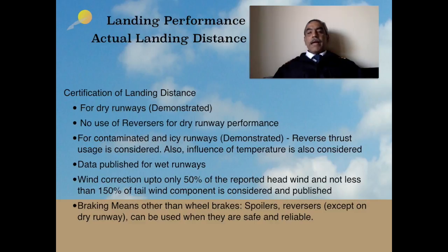For contaminated and icy runways, again, I'm sorry, this also has to be demonstrated. Except for wet runways, data has to be published. Whereas icy runways, the performance has to be demonstrated. Reverse thrust usage is permissible, considered. Also, influence of temperature is also considered. That means different temperatures are considered.